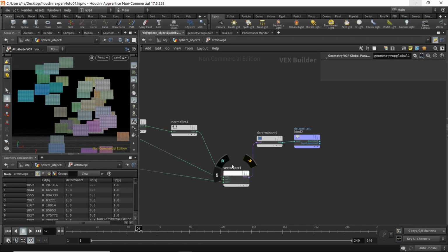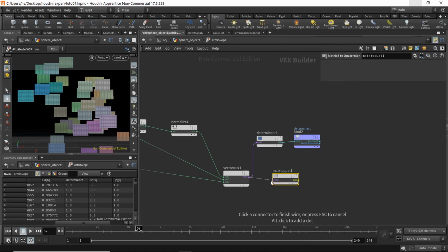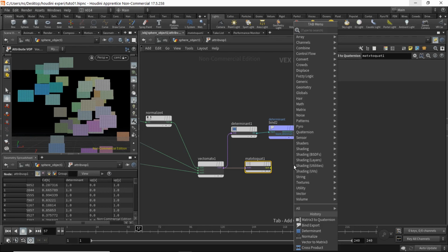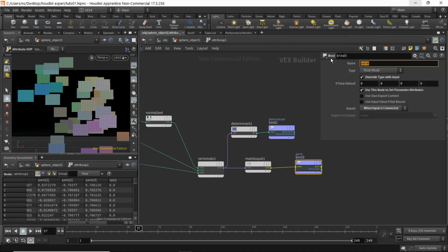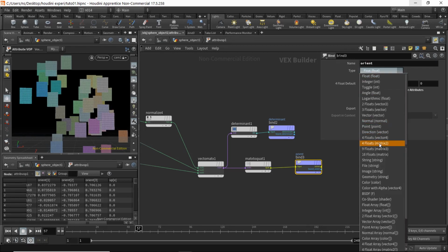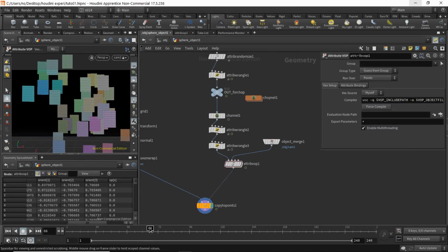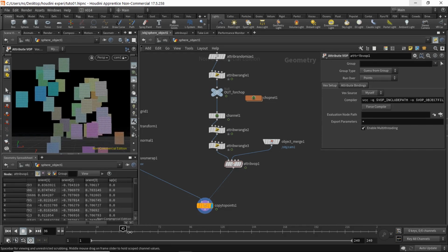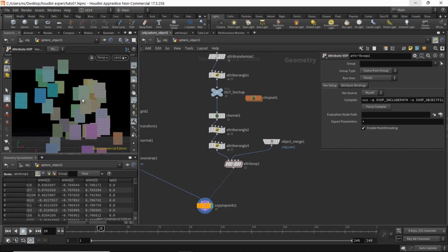So now that we have calculated a proper matrix, let's create the orient attribute. So matrix to quaternion. Let's export it as orient attribute. So this is going to be an orient attribute, and the type here is going to be 4 float vector. This is going to give us a lot more stable result, and even with the extreme camera angles, this is not going to flip or give some weird rotations. However, one thing, we need to rotate it by 90 degrees.